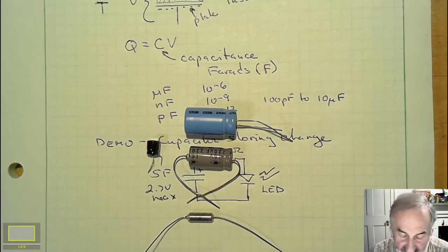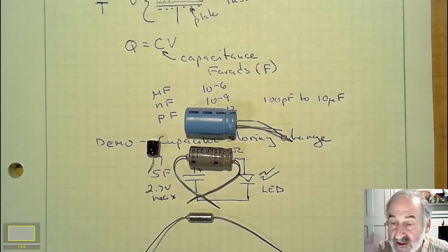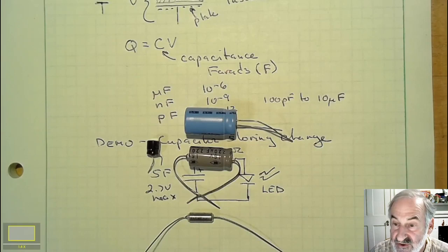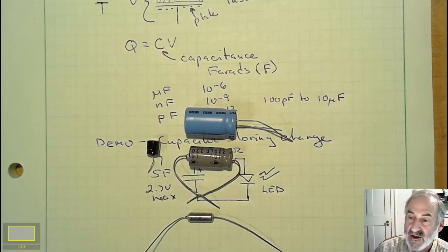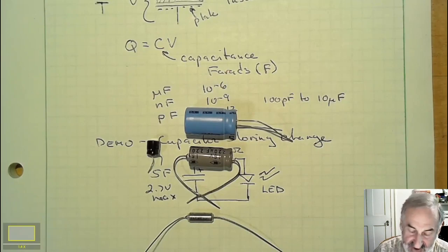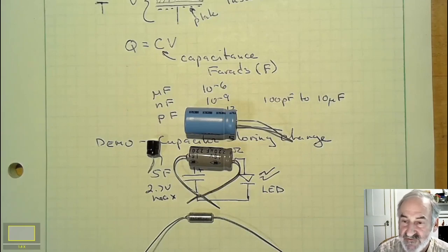And of course tolerance, which is exactly the same as resistors, except that capacitors tend to have looser tolerances. We typically use plus minus 5% resistors. A plus minus 5% capacitor would be unusual and expensive. Our capacitors are typically plus minus 10, plus minus 20. For an electrolytic capacitor, you can often find minus 10, plus 50, because typically they're used in applications where you don't care about them being too big.